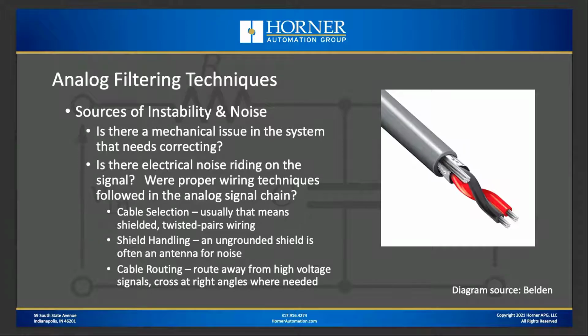If we've got shielded cabling and we haven't grounded the shield properly, then that shield is just acting as an antenna for our signal wire. That's obviously not what we want. So we're going to want to ground that shield at the best earth ground we can find, and preferably, if it's on the sensor side as opposed to the instrumentation side, such as the OCS side, that's better yet.